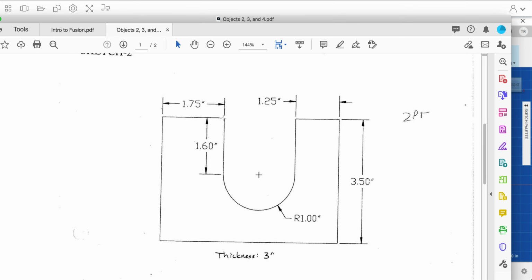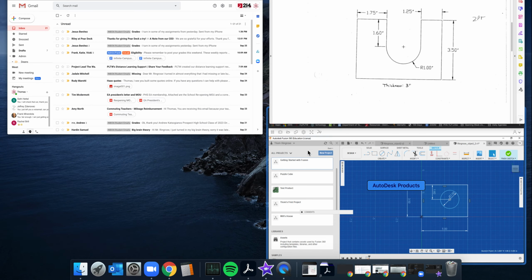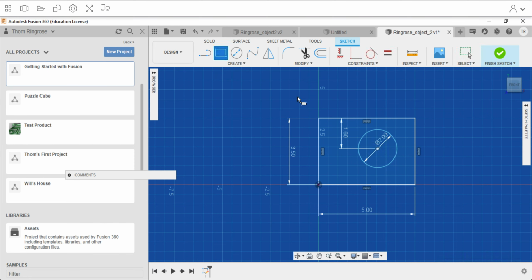Let's look at our top rectangle here. So we know we need to be 1.6 inches tall, and we need to be 2 inches wide. So I'm going to radius of 1, my diameter is 2, so that tells me edge to edge is 2 inches. So let's make a square, rectangle. Rectangle type shape, 1.6, tab 2.